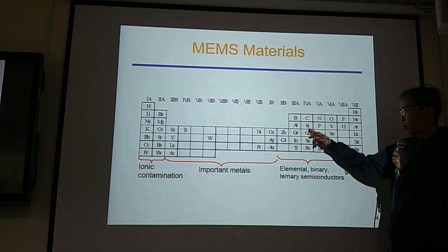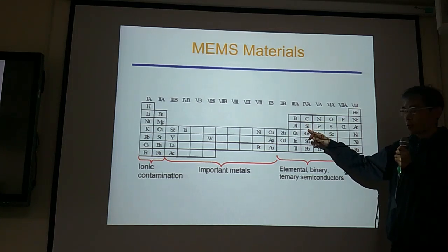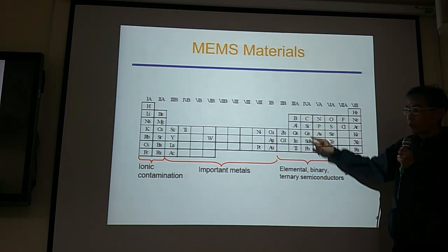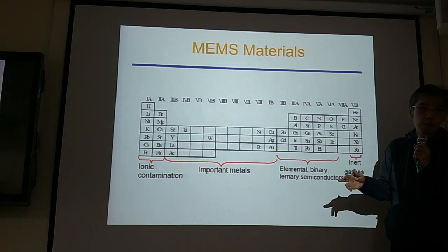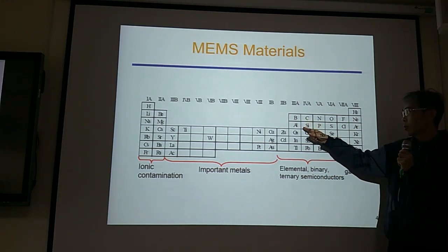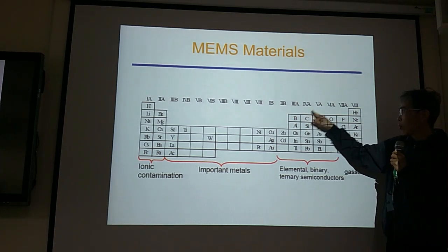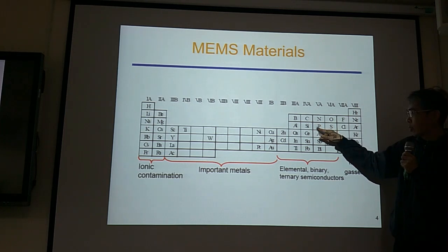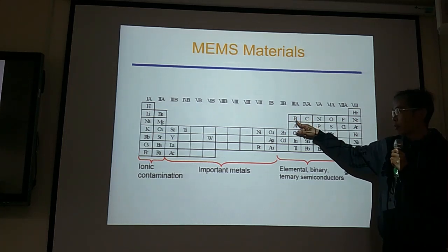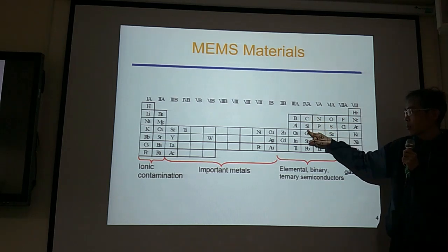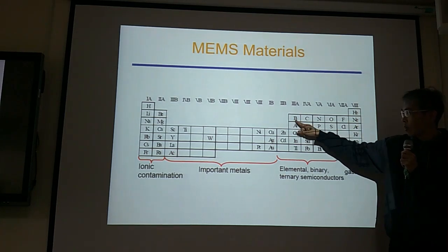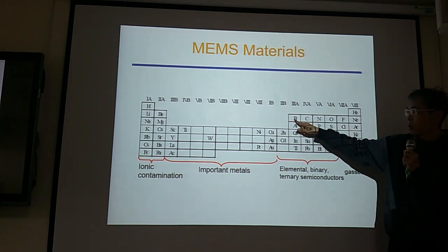So silicon is our silicon wafer material. So now everything happens on silicon wafer. It belongs to the 4A family. But we want to turn it into a conductor, so we need to put either 3A family boron or 5A phosphorus inside the silicon to make the silicon a conductor. So if it's boron, remember, the outermost orbit will have 4 electrons for silicon. The outermost orbit will have 3 electrons for boron.